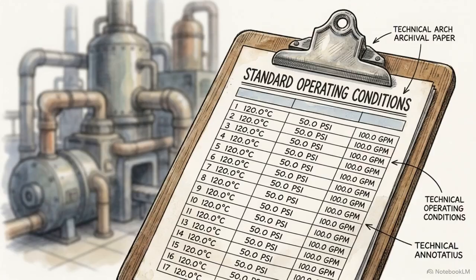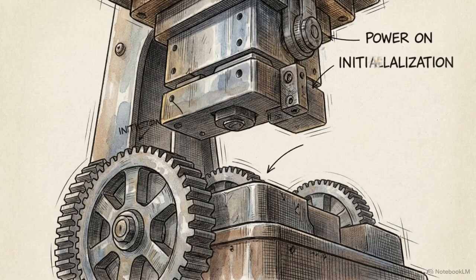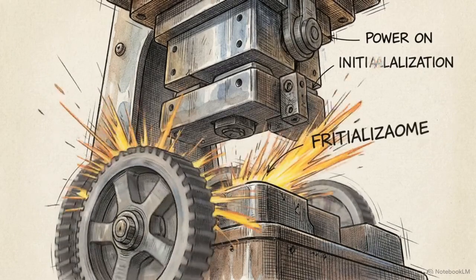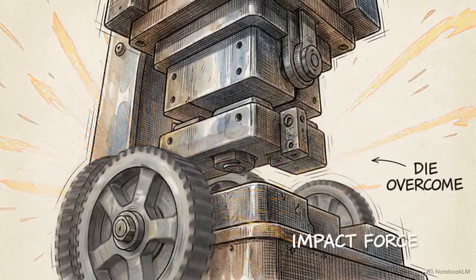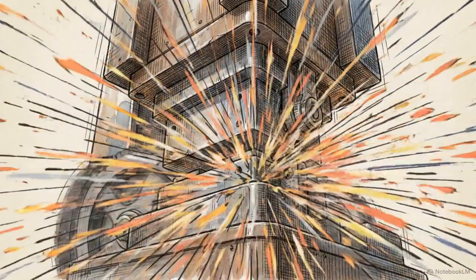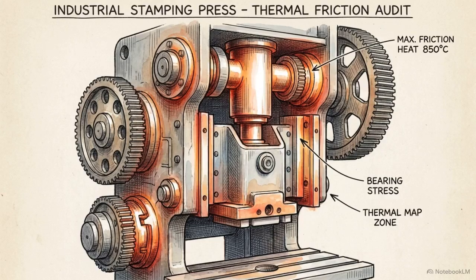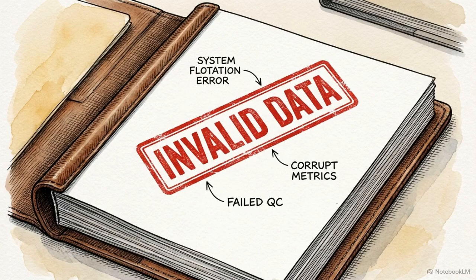Another major pitfall is measuring equipment exclusively during normal, steady-state production runs. This creates a massive operational blind spot. To find the real waste, you have to monitor the systems during abnormal periods. System startups and shutdowns put sudden, heavy mechanical stress on equipment, and these transitional states frequently reveal the facility's largest hidden energy losses. If you extract perfect, highly precise measurements from the wrong operational window, you will end up with mathematically flawless, but practically worthless conclusions.